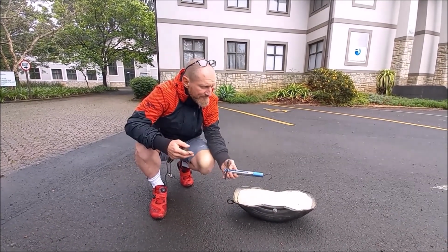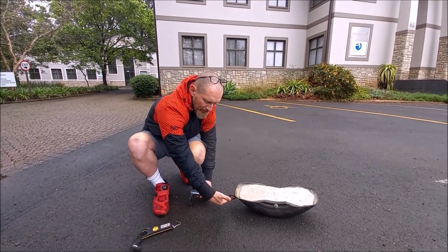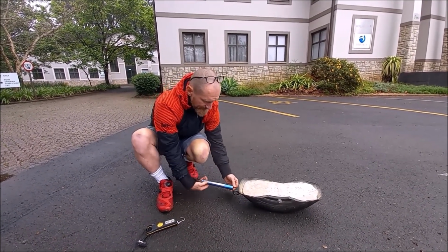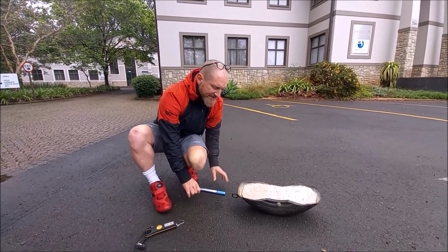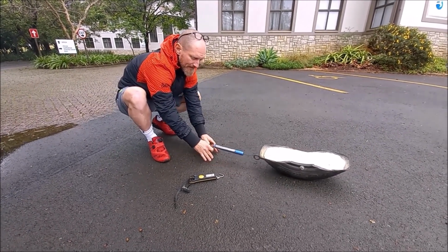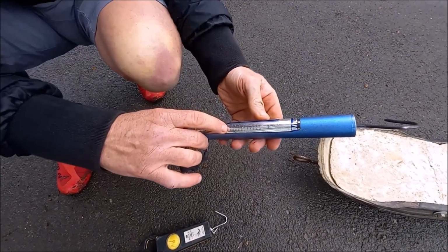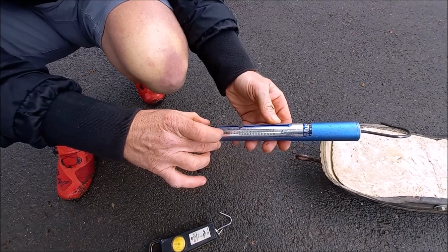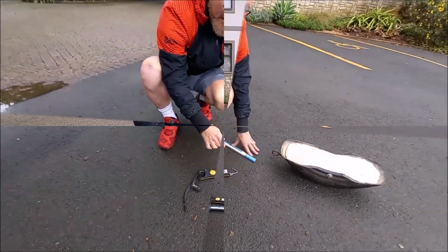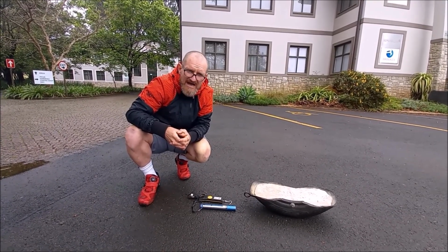But in very simple principle, all we would do is we would take this known mass tire, we would make sure we pull level to the center of mass of the actual device, the actual object. And as we pulled it, we would take a reading off the scale. So in this particular pull, we could see straight away that we ended up with approximately 11.5 kilograms pull force in order to move that scale along this surface.